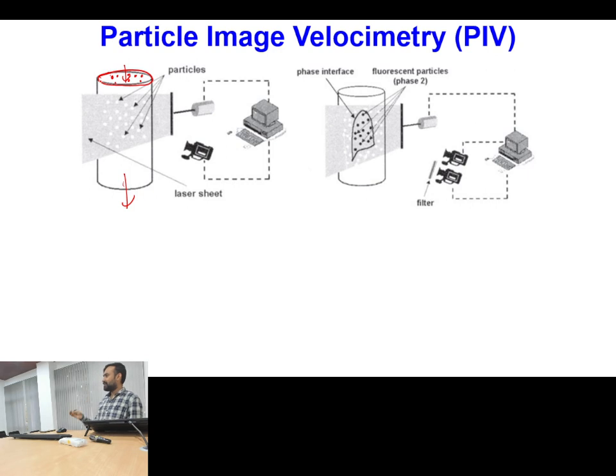We know that whenever a particle is placed in a flow field, it has some response time. But the particle is selected so that its response time is negligible in comparison to the time scale of the flow fluctuation. Because of this, whenever the flow changes, the particle will immediately adapt to the flow situation.